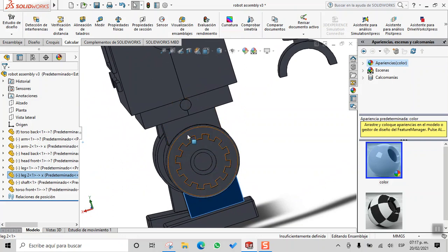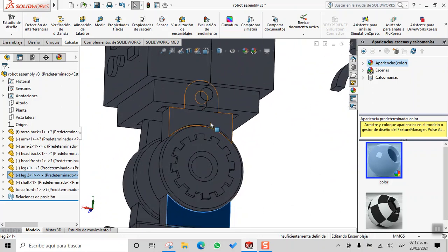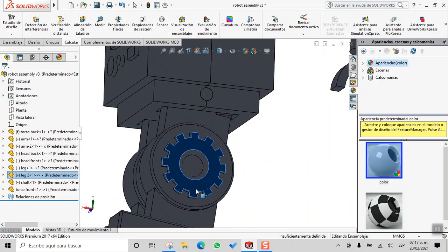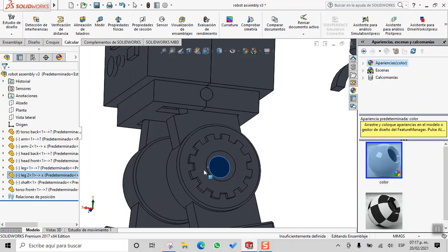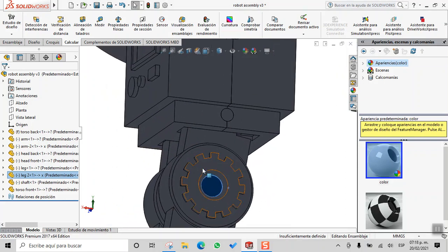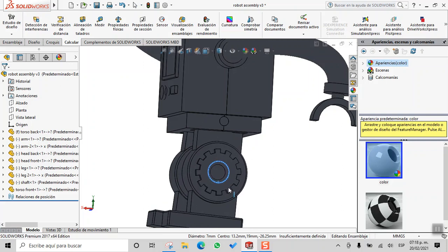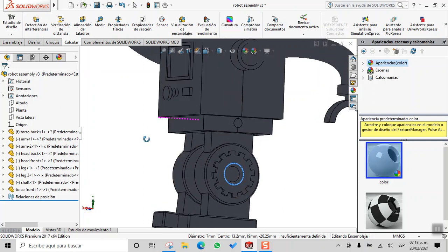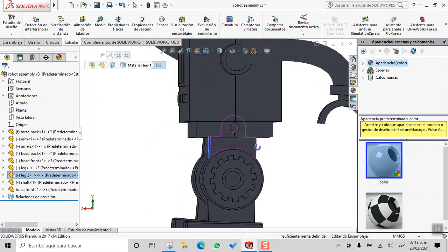So this restriction is a little bit more, well, it can help us look or simulate how the parts touch. So in a regular assembly, this part or this leg will collide with this front part, which is the torso front, and it won't move any further. So to simulate that, we can add a range of motion that it's allowed. And to do that, we will be selecting a face, in this case this one, and a parallel face,